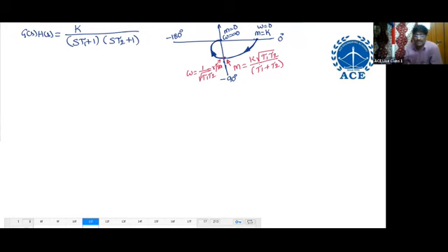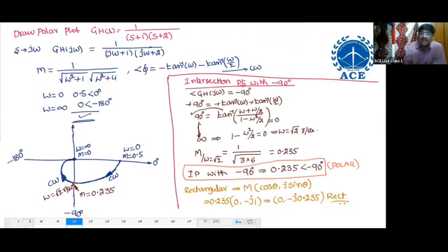If you have any doubt, substitute the tau 1 value, tau 2 value and K, and you will get the same answer. What are tau 1 and tau 2 here? If you convert to time constant form, GH equals 2; take 2 common, and 1 by 2 means 0.5. So 0.5 by (1 plus s)(1 plus 0.5 s).